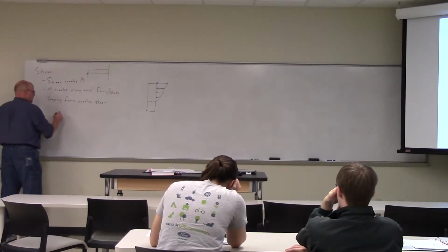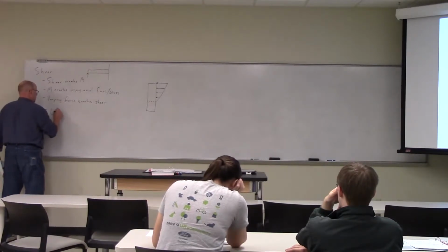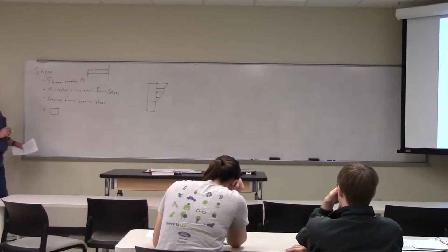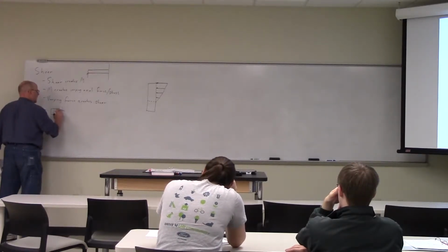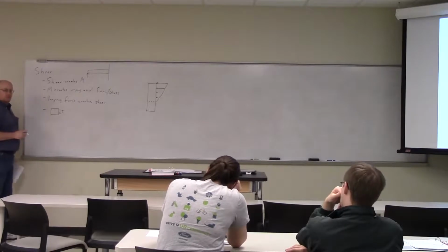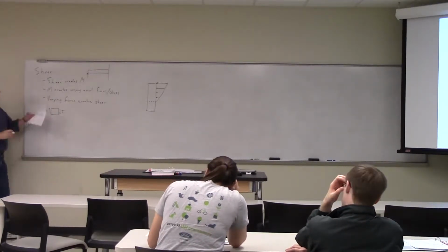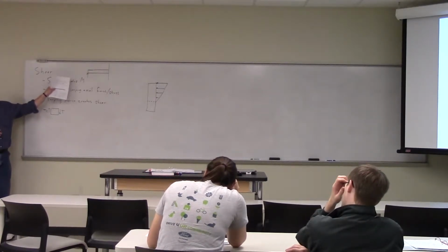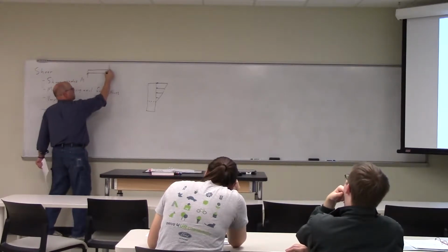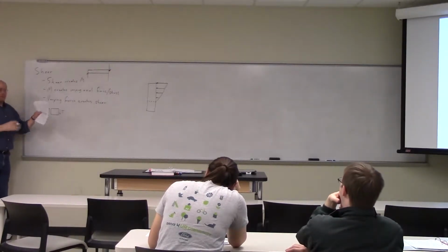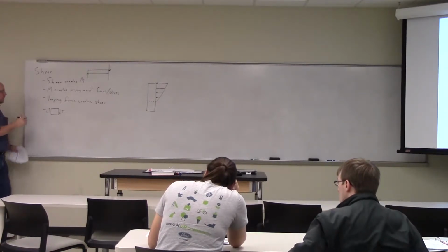But what we're going to do is take, oh, and one more thing. If I take a little block and I want to know the shear stress, tau, acting on that block due to this applied force, I'm creating a tau here when I apply that force, because there's a reaction force down here in the downward direction. So I'm creating a shear on any element within there.